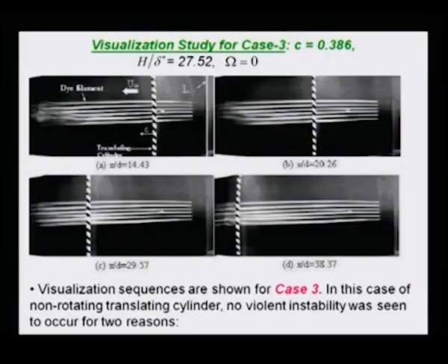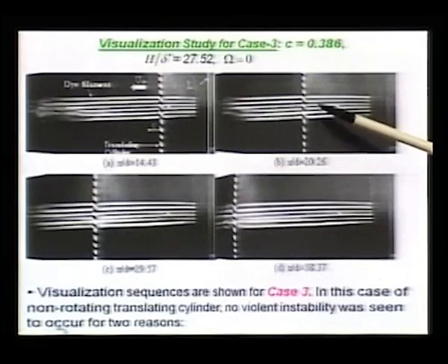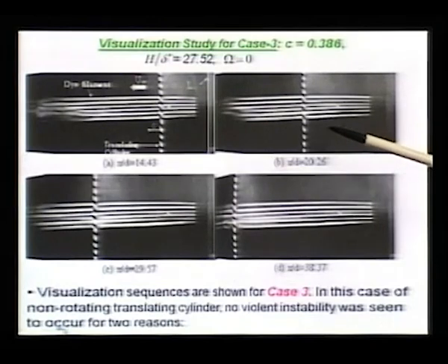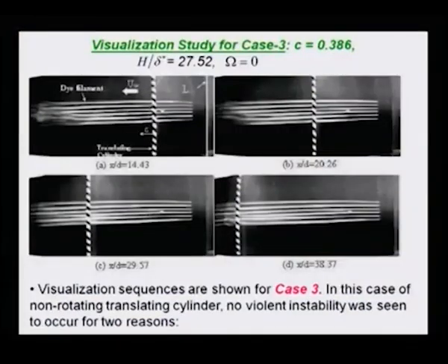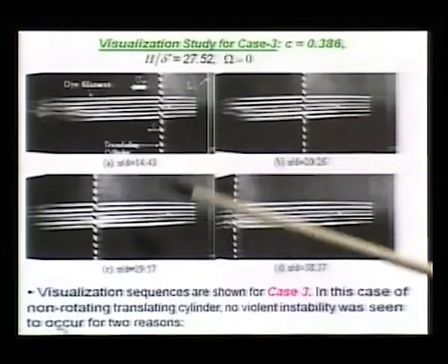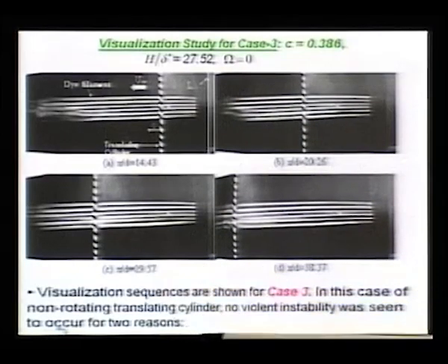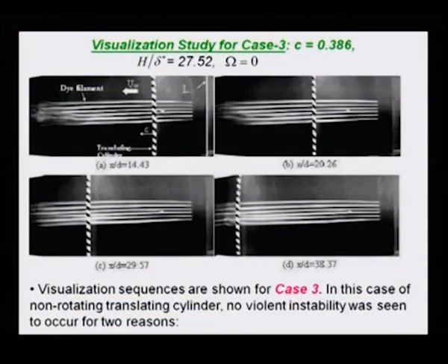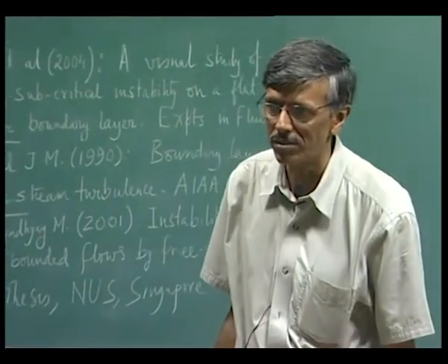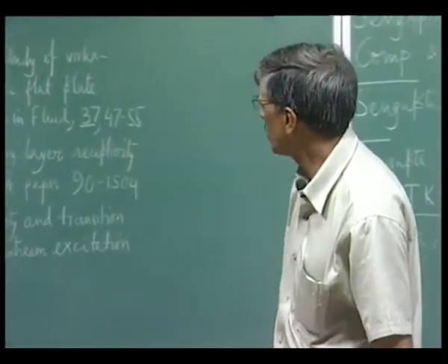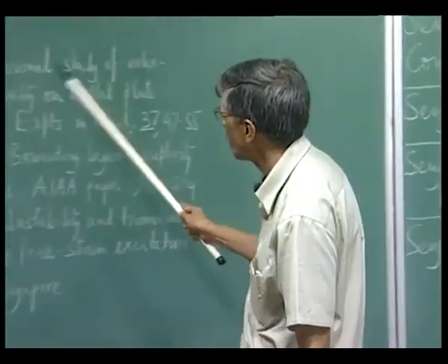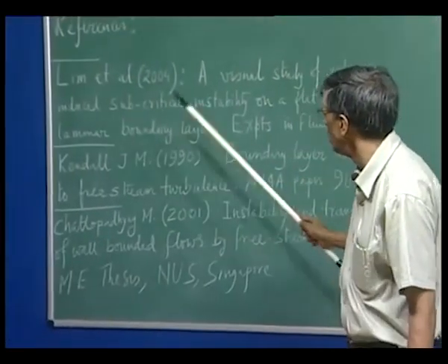Even in this case, where we do not rotate it, there might be vortex shedding, but because of this large distance of separation between the vortex that is in the free stream and down below, what you are seeing essentially is only the displacement effect. That is not good enough to create the instability. That is why this whole phenomenon we have called vortex induced instability, right.